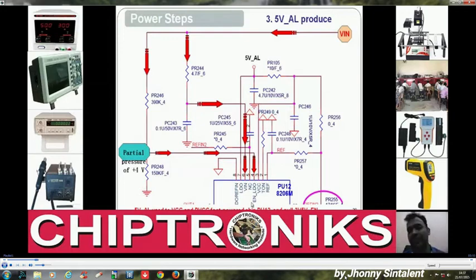There are two kinds of regulators. We'll discuss in today's class also, the two kinds of regulators. One is linear regulators, another is switch mode power supply, that is PWM regulators. So with a linear regulator, you don't have to be concerned with MOSFETs, turning on of MOSFETs. Whereas if you have a switch mode regulator, you have to be concerned with switching, because switch on, switch off, switch on, switch off. Whereas in linear regulators, it directly generates a voltage.